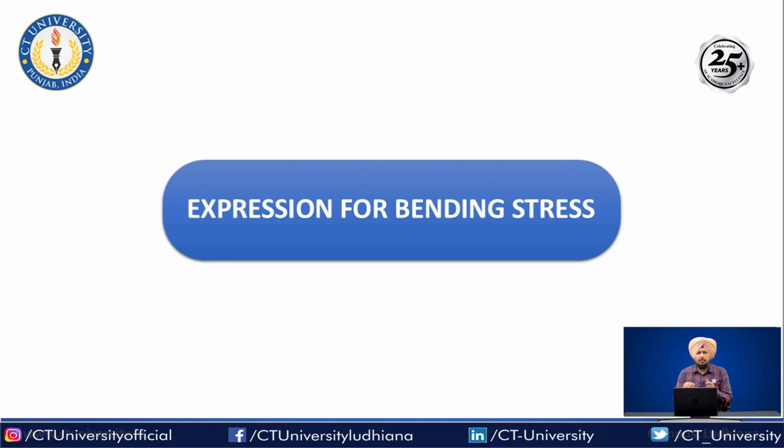So bending stress in the material depends upon a lot of conditions. It depends upon the working conditions and loading conditions, that is, how much load is applied. It depends upon the geometry: what is the geometry of your beam, what is the moment of inertia. And then it depends upon the material, which material we are going to take. All these properties or parameters will be considered in one single expression, and it will help to find the maximum bending stress, and also the stress at different locations.